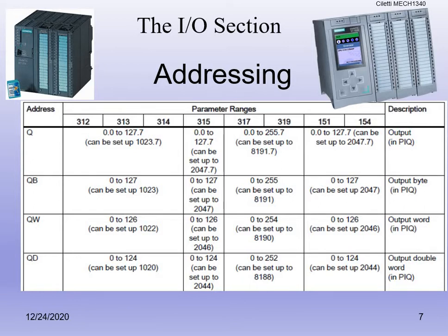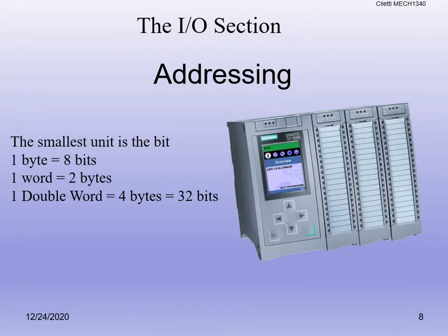Okay, and where the ranges can go when we go above 128. We're not going to do that. Some places you might work in industry. Just know that the difference between Q and QB is where the IO address slots are. Once you go above 128, we start changing the tag on the address. So how we address and what it means, we're going to get into.